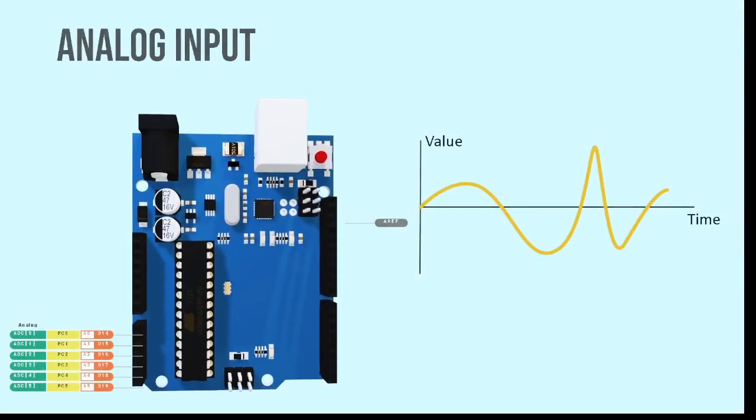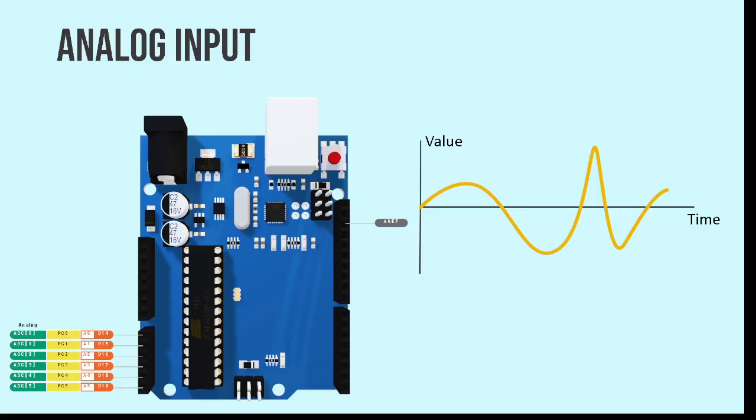Okay, in the other part, we have analog signals, right? For example, in the Arduino Uno, we can read signals from 0 to 5 volts, every value in between, right? Not every value. We're going to study what our resolution is, right? But we can read a lot of values there. We can read, for example, 1.5, 3, 2.3, 3 point whatever. We can do that in some pins, not in all of them. They are all grouped in this part of the Arduino Uno. They are the analog inputs.